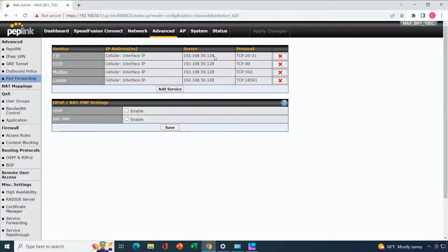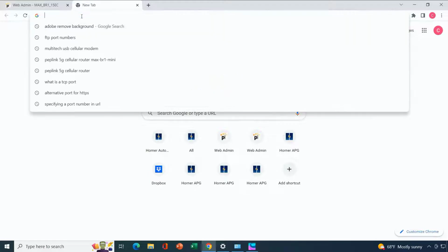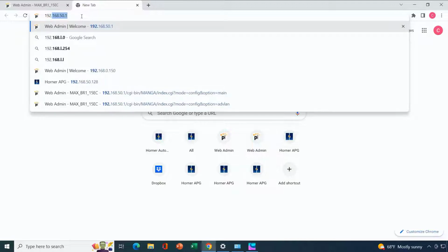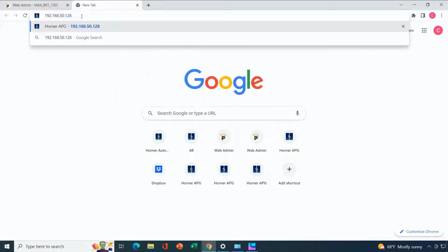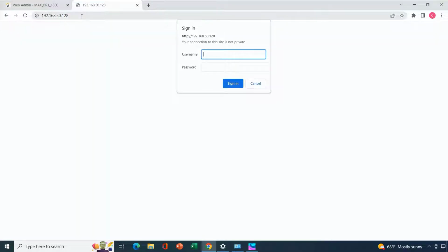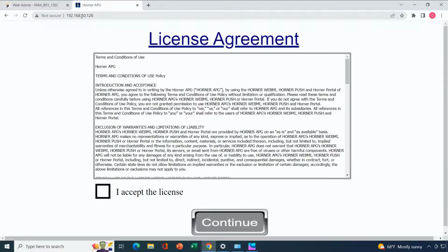So now let me go ahead and demonstrate using WebMI on the local area network. I'm still, next to my machine, logged in to the local area network. Let me open up another tab with my web browser, and I'm going to use the local LAN address of my OCS so I can access WebMI. Okay, so there we go. It's asking for my login credentials. These were programmed into Cscape. So I use my login credentials. All right, and boom, here you go.